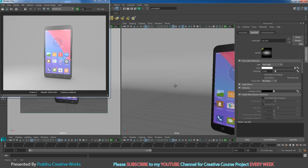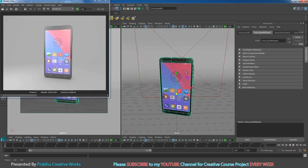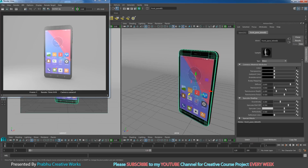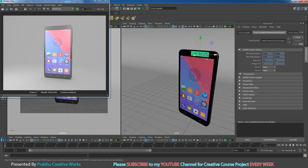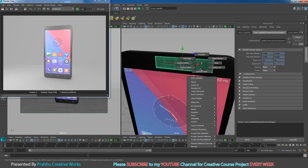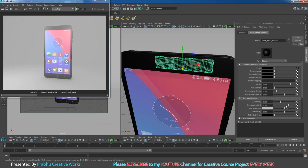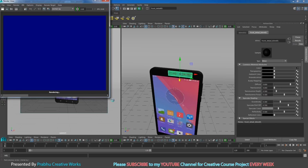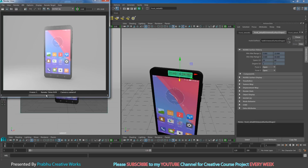So I will select this object over here, right click and choose material attributes. Here you need to reduce the specular color a little bit. Then you want to select this one also, front_detail. Right click and choose material attributes. Here also you need to reduce the specular color a little bit. Now I keep this image for comparison and click render. Now you see our specular color is reduced. I will compare like this.